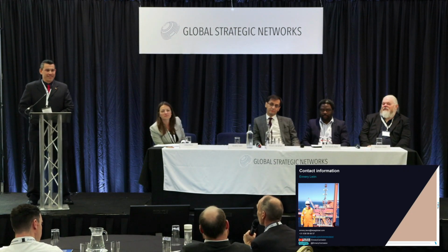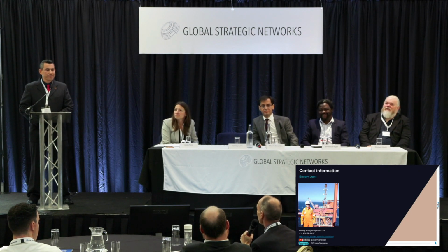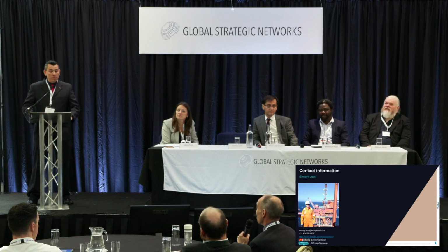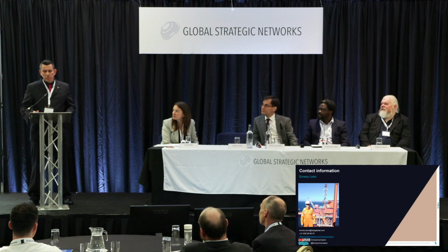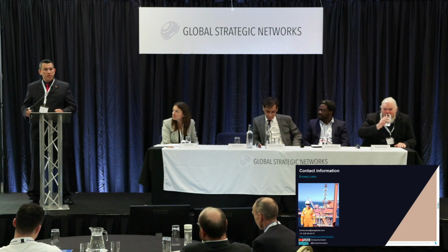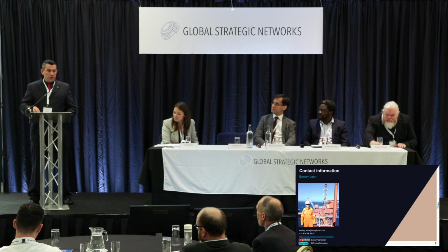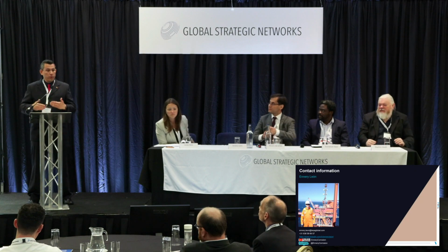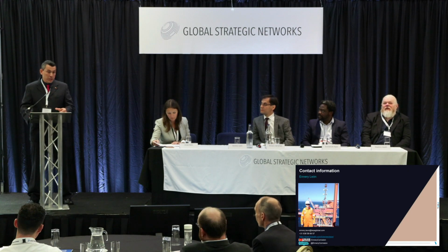Mark Jordan with Champion X. Just a question: what's your view of side stream ER probes, temporarily installed equipment for trials and optimization? Do they have a role to play, or are they limited by the fact that they're temporary? Definitely. You can use ER probes for special projects. If you don't have an access fitting, you can use them as a temporary solution to measure the corrosion rate while you are doing some trials with a corrosion inhibitor or different injection rates.